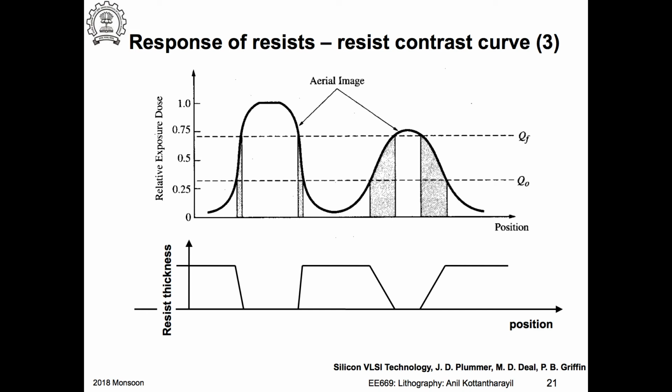So let's say I want to do a lift-off process. The lift-off worked this way: you have the photoresist and you have developed it. Okay, and then you're going to deposit metal on top. The condition was you are not going to etch the metal, by the way. Now this is for situations where etching the metal is not practical. For example, gold is very difficult to etch, and you need aqua regia, and aqua regia may attack other things on the wafer.